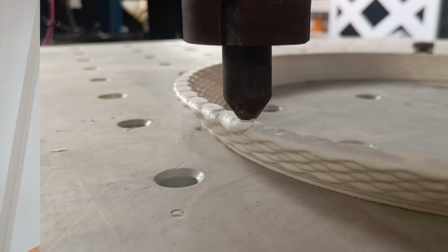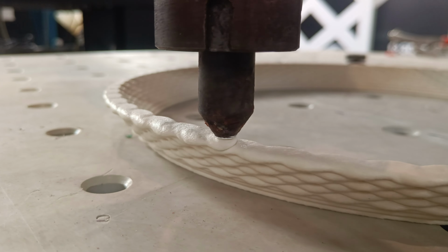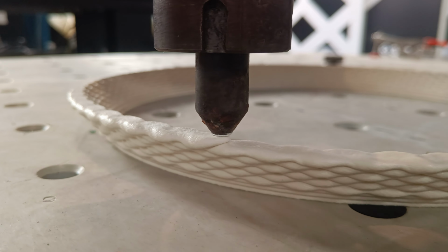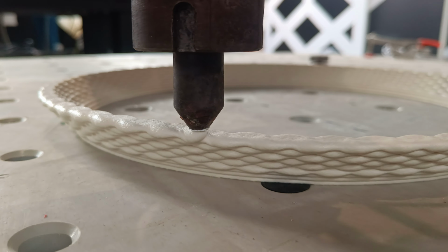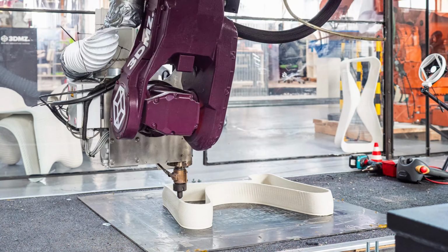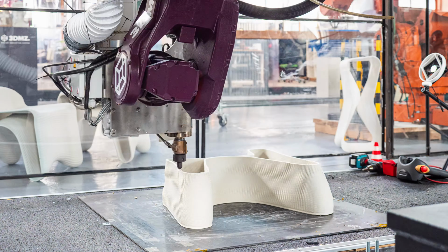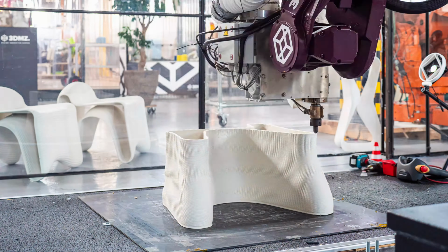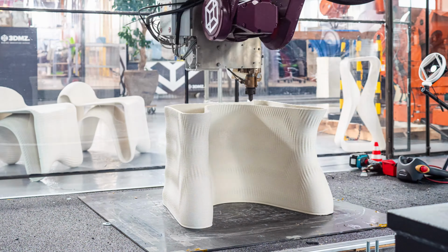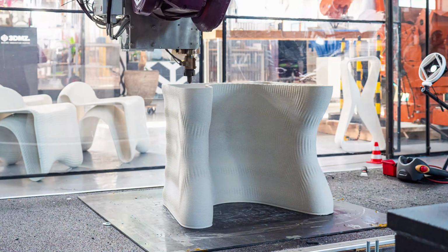The surface is another big difference. With robotic 3D printing, the layer lines are not something you can hide. They are thicker, they are bigger, and most of the time you want to make them part of your design. So the way the paths are drawn can give extra texture, reflection, and character. Then there's heat and time. The material stays warmer for way longer, so that can become an issue. For example, if you are printing really thin lines or straight walls, the objects tend to twist or bend. So curved or thicker layer lines tend to work better.